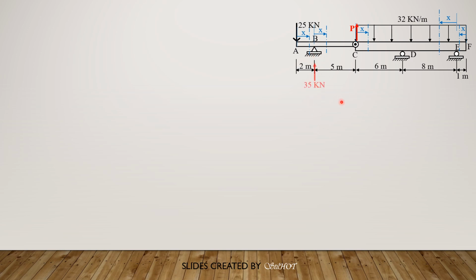It is 35. So summation of forces in Y, so 10, not a function of C. Then we have 10 upward, action reaction. Then summation of moment about D equals 0. So P times 6, clockwise, equals reaction at E times 8. So 6P divided by 8 is 0.75. So therefore, the reaction at E is upward 97.5 plus 0.75 of P.